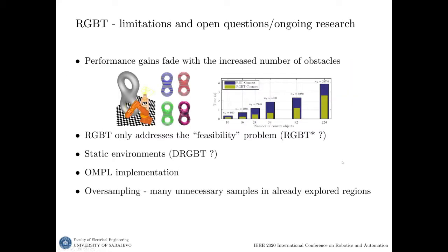It is important to state the limitations of the approach. First, the current algorithm assumes that the environment is decomposed into convex obstacles. Moreover, we observed that the performance gains decrease when the number of obstacles increases. We are currently addressing this problem by exploiting the underlying decomposition of obstacles using bounding volume hierarchies within FCL library. These bounding volumes are inherently convex, and thus the need for initial explicit convex decomposition can be relaxed.